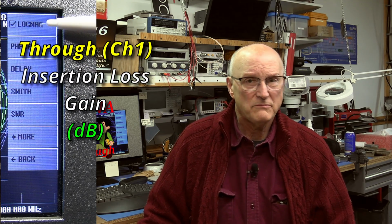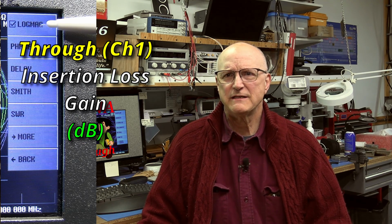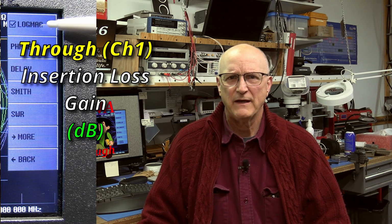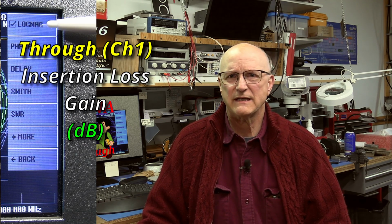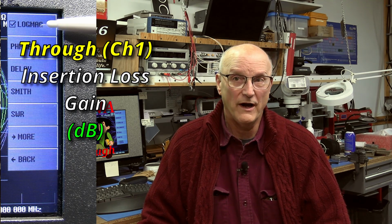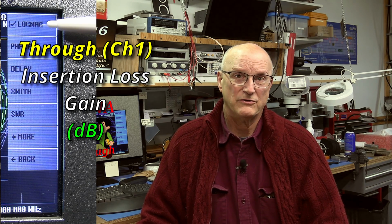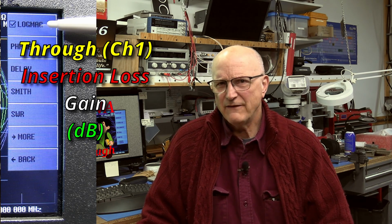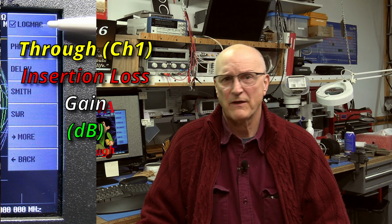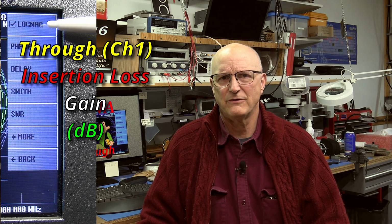In through mode, also known as using channel 1, this is the insertion loss or gain expressed in dB. It tells us how much of the signal that is being sent out of channel 0, in other words port 1, is getting to channel 1, also known as port 2. It is negative if we're losing signal, which is typical for insertion loss. The more negative the number, the less signal is getting through.